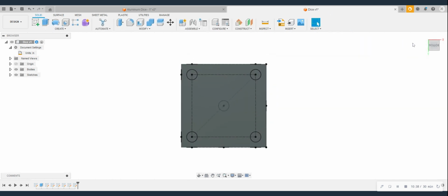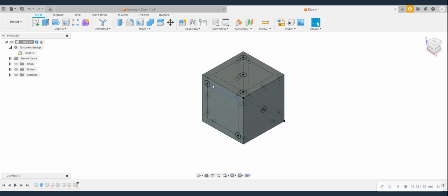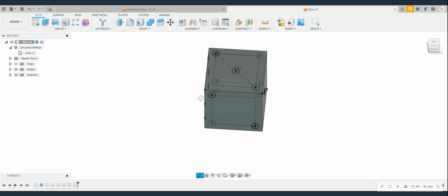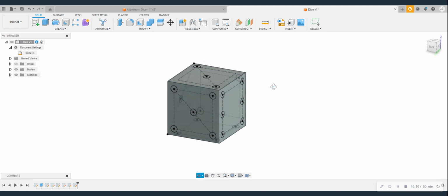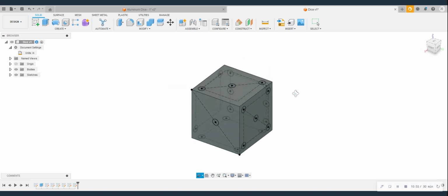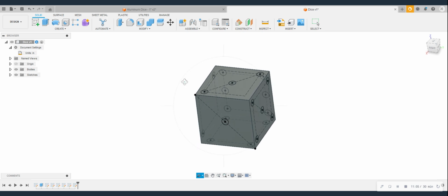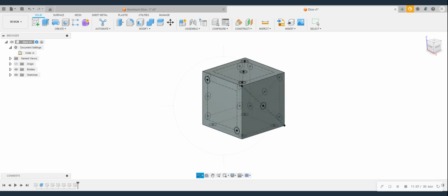Okay, finish sketch, and if we go to the home view, we can see now that we should have a sketch on every single face. So I'll start to orbit around. I can use the orbit tool if I so desire, and I can just double check my work, make sure everything's good. A quick check you can make is if you add the opposite faces of the dice together. So for instance, where my cursor is right now, I'm looking at a 5. It should always add up to 7 with the opposite face.